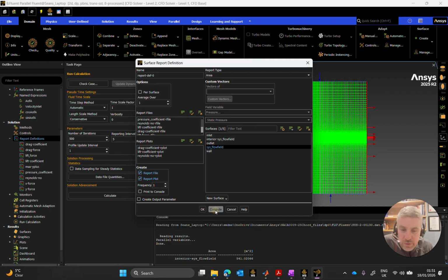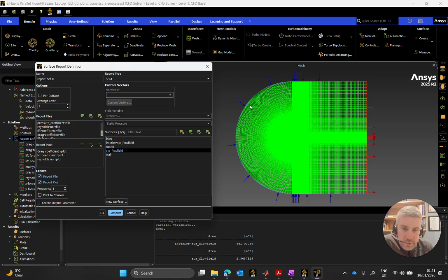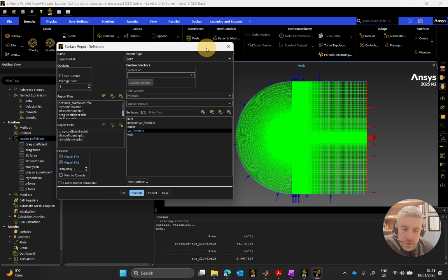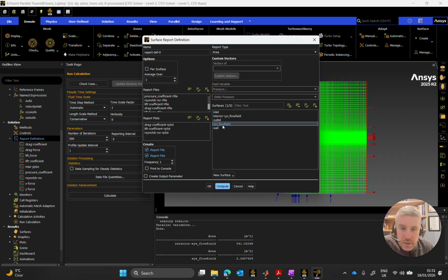Similarly, if I go to system flow field and hit compute, 2.34, slightly better, but it's still too large, given that, if you recall, the diameter here is 0.75 meters. We're running 2 meters by 1.5 meters, so we're probably in the region of 0.57, 0.58, maybe a wee bit more, maybe up to 0.6, but we're in that region. We're not near 2.3489, let alone 541. So that's not what I'm looking for.